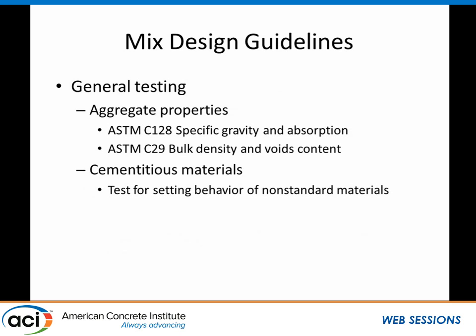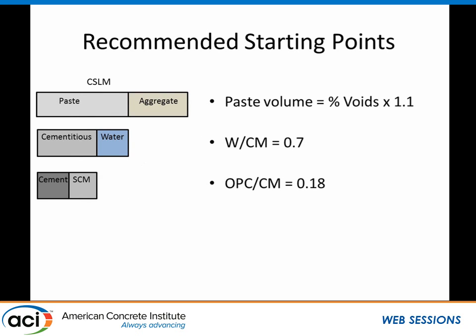Number one, we addressed the initial testing of the materials strongly, so that they realize it's really important to characterize the specific gravity and absorption of your particles, and the bulk density to get your void content, and so forth. And these standardized tests help you get those parameters. And then there's a test for setting behavior if the set time happens to be important.